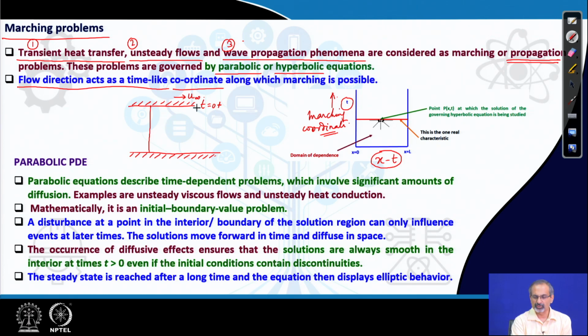Because it is a viscous flow, the flow cannot slip on the upper surface, and therefore, along with the wall, all the fluid particles adjacent to that wall also start moving with velocity u infinity. After a while, you will find that momentum percolates from the moving fluid to lower layers like this. And finally, after a long time, the velocity distribution may look like this.